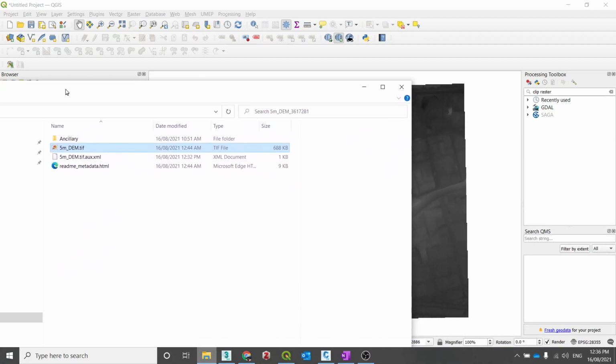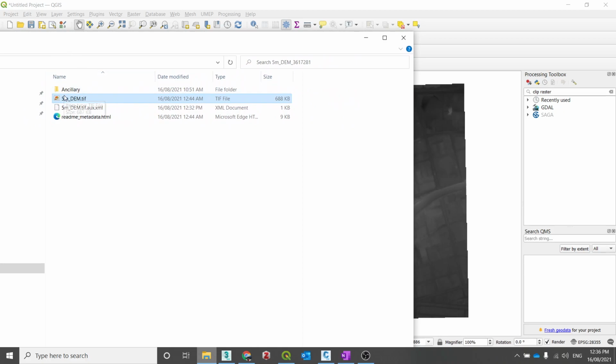Now when you do that, the first bit of data that you pull into a scene, you'll notice down here that the EPSG code will change from WGS 84 to the EPSG code which is associated with your coordinate reference system. So this project now kind of knows that most of what you're going to be working in is this projected MGA 55 coordinate reference system.